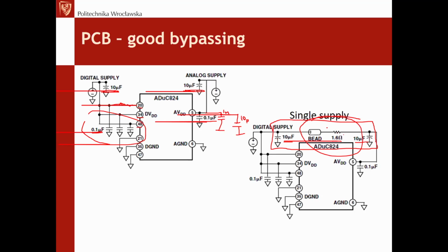Yet we have today quite universal components, which are ferrite beads. We talked about them in the beginning. Ferrite beads are special types of inductors, dumping, with low DC resistance but quite a decent impedance at high frequencies. This means that the high frequency switching noise present at this point will not be present right after the ferrite bead, because the ferrite bead impedance together with those capacitances will filter out those noises.